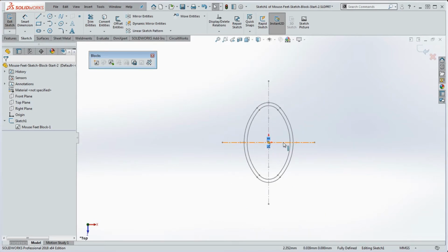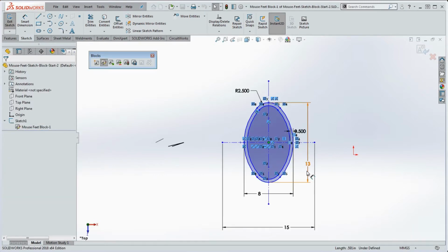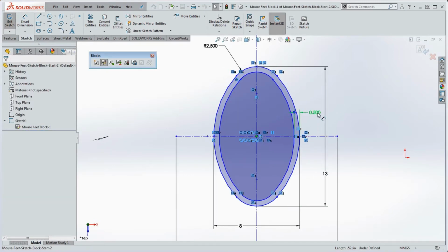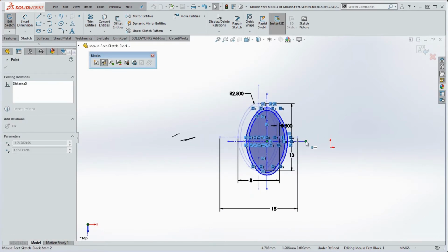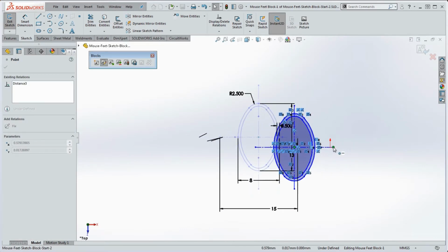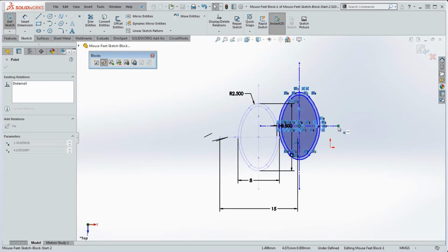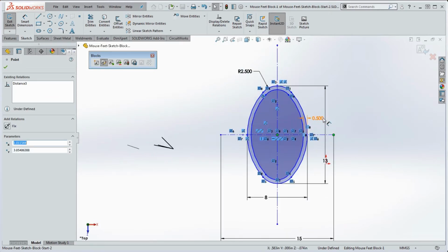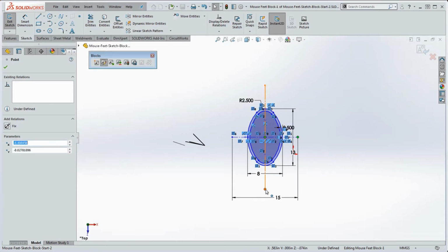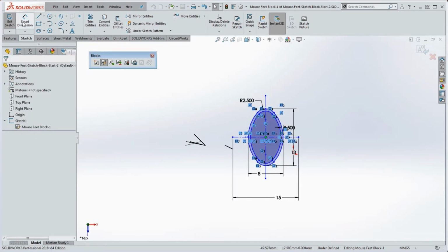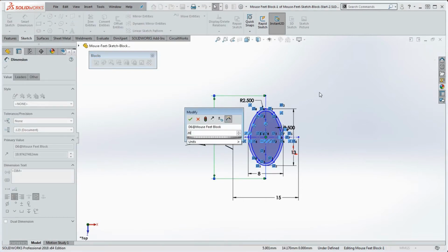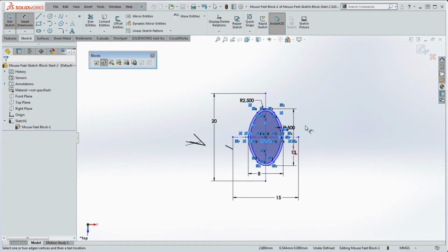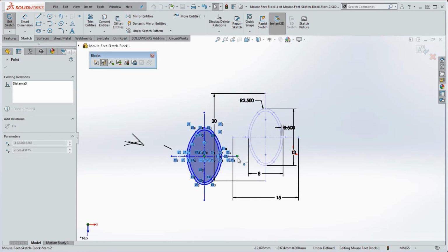And while we're in that sketch, double click on these entities that define that block. Now we have those in place. So now if we move this around as a block just to see if it's fully defined, it still is fully defined. And we seem to have lost this dimension over here in regard to the length. If you remember before, it was an arbitrary dimension on that center line, we're going to make that 20. So now when we move this around, it all moves around as a block.